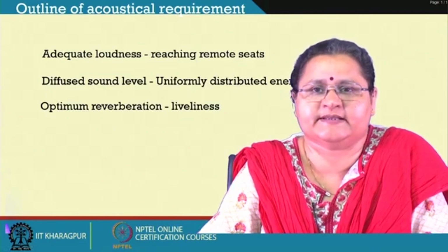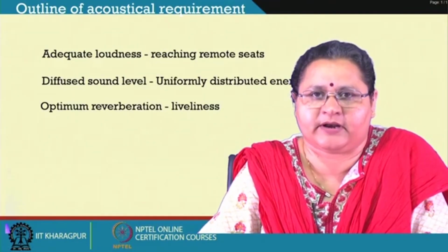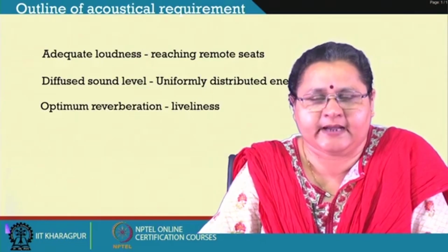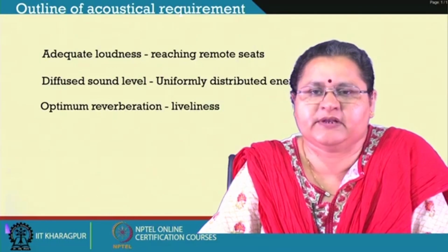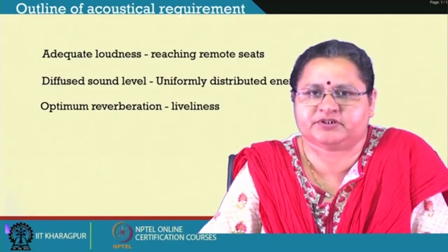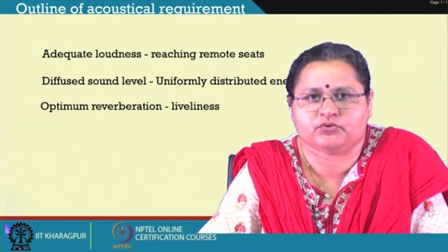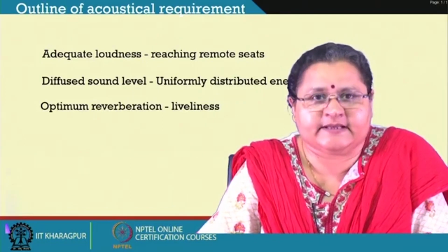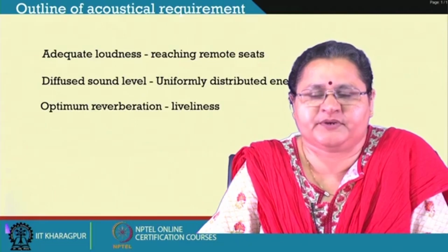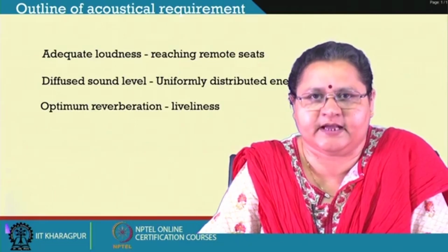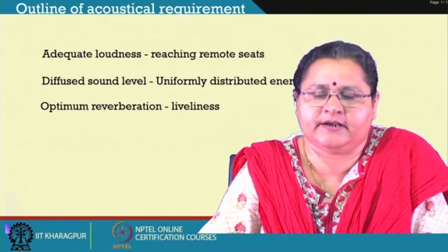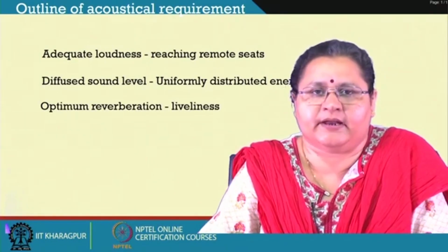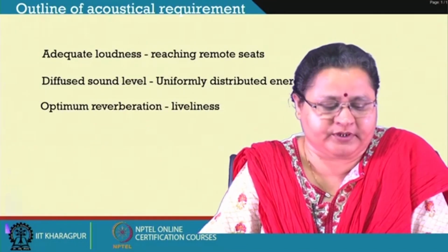The way you plan your reflective surfaces, your diffusive surfaces and your absorptive surfaces, you will get different reverberation times and different sound quality within the space. So, for achieving the optimum reverberation time which is desired, which has been given earlier in the lists and graphs, you can refer to them and start from that point.